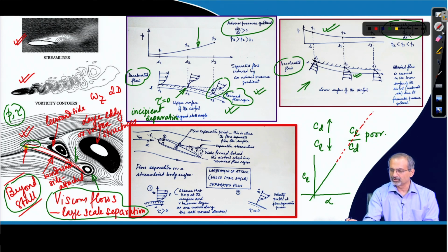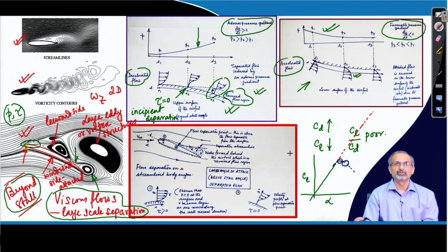So, the Navier-Stokes solution that you see over here predicts a stall, it droops down, and you are probably looking at the flow somewhere here or maybe here, where it has already stalled and you have moved into the post-stall region, and only Navier-Stokes equations can handle that, not even boundary layer equations will be able to handle it. So, we are negating most of the models in order to capture a physics of this kind. That means, thin airfoil theory cannot capture it, potential flow theory cannot capture it, because the flow is highly rotational.